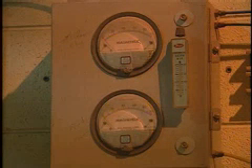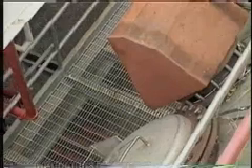Decreased pressure drop is usually due to partial or complete collapse of the fixed bed because of corrosion of the support grid. This will also cause increased emissions.